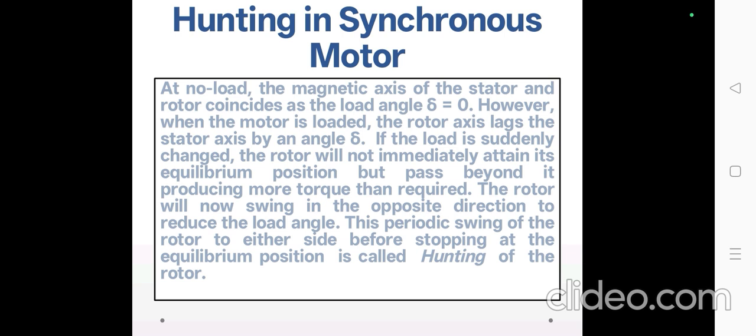If the oscillations continue for a longer period, there are large fluctuations in the current. If such variations are synchronized with the natural frequency of oscillations of the rotor, the amplitude of the swing may become so great that the motor may come out of synchronism. At this instant, mechanical stresses on the rotor are severe and the current drawn by the motor is also very large. So the motor is subjected to mechanical and electrical stresses.